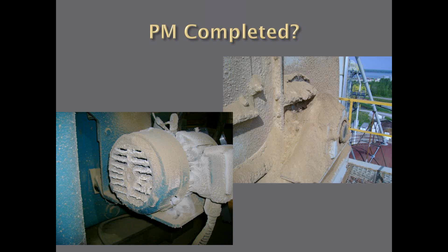I go up there on Saturday morning to take a picture of the St. Lawrence Seaway, nice sunny day. This is what I find. Now, you think the person did the PM on this bearing the day before. I took my finger, dug down, found the grease through that crusty meal. The PM wasn't completed. So I asked them on Monday morning, why'd you check off the box that you completed it and it wasn't completed?